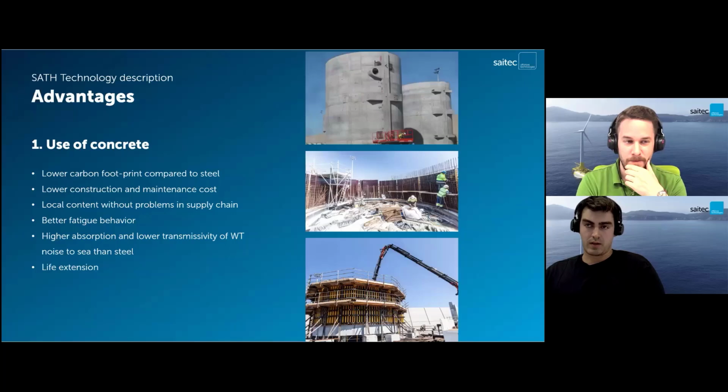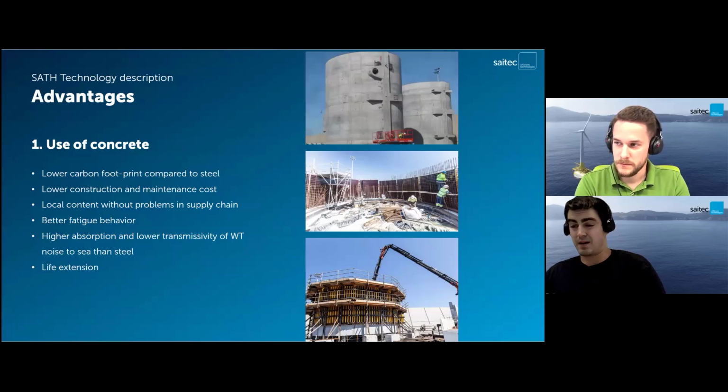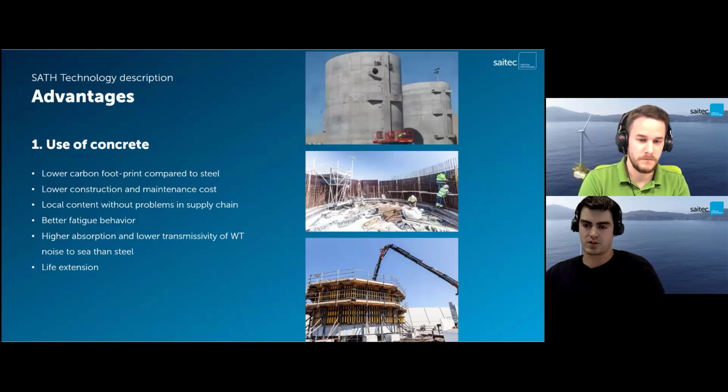Concrete, when compared to steel, has a lower carbon footprint, so that's the first benefit. It also has a lower construction and maintenance cost. Then it helps to enable local content in a project, and this is valuable when you want to reduce the associated risk of importing the raw material. And in terms of structural performance, concrete has a better fatigue behavior, which can lead to an extended lifetime of the structure.